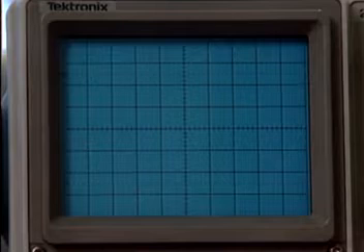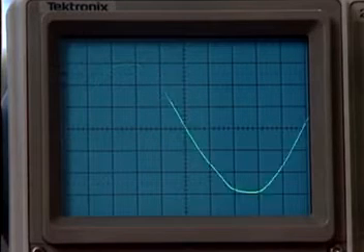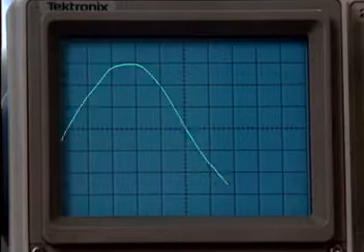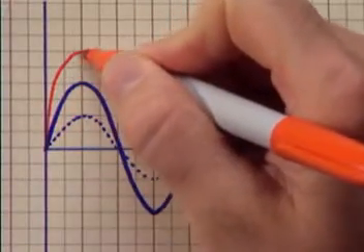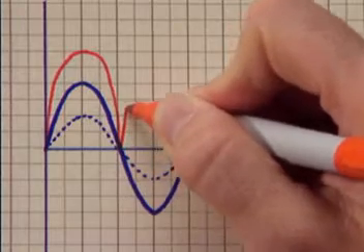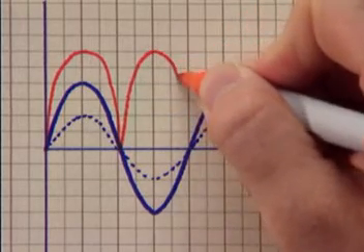But for an instantaneous moment in a given cycle, the value of the current flowing at that instant is directly proportional to the magnitude of the voltage at that same instant. Since all direct current rules and laws apply to alternating current resistive circuits, the AC power may be calculated from the measured voltage and current. If the instantaneous values of voltage and current are multiplied and plotted, an AC power waveform is constructed.